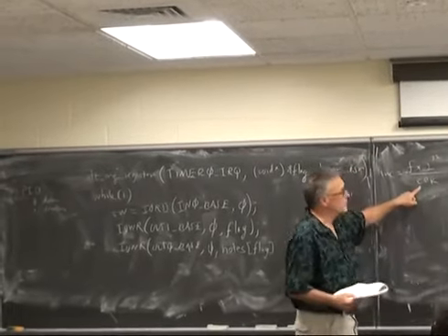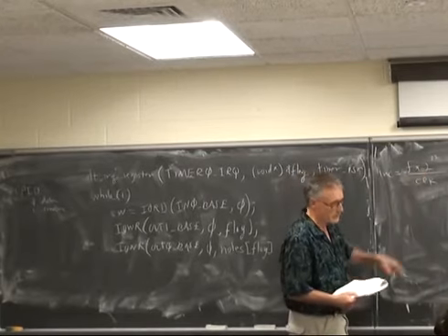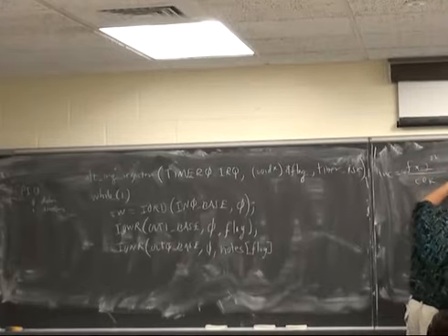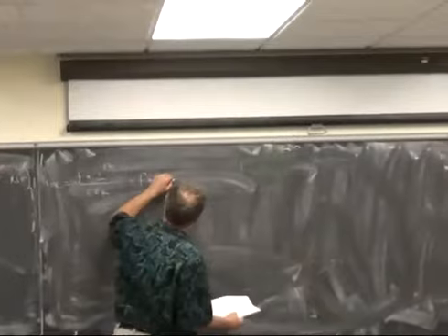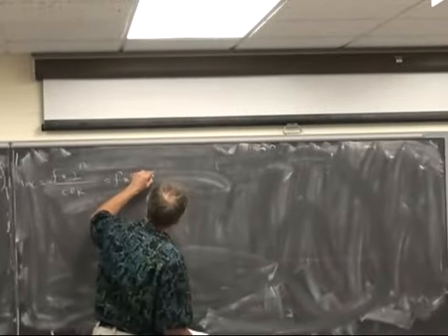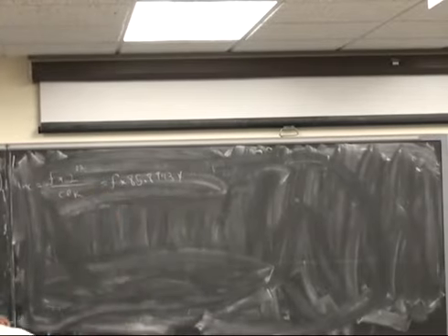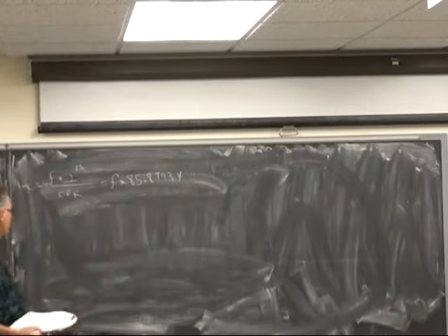For a 50 megahertz clock and for a 32-bit direct digital synthesis register, this works out to f times 85.89934, but that's pretty darn close to 85.9.